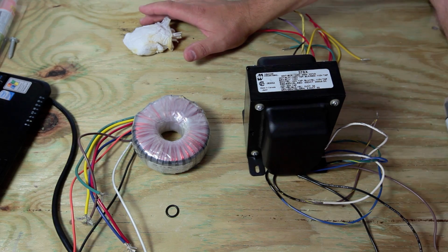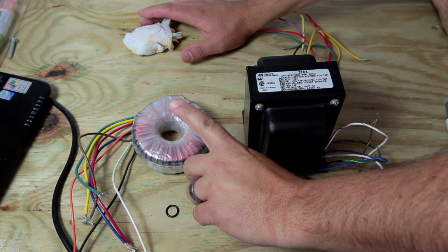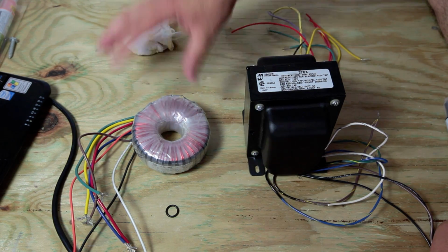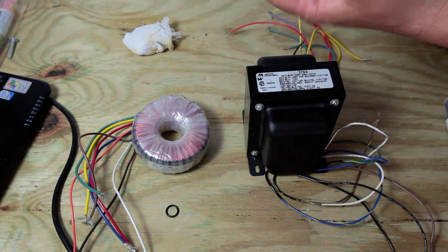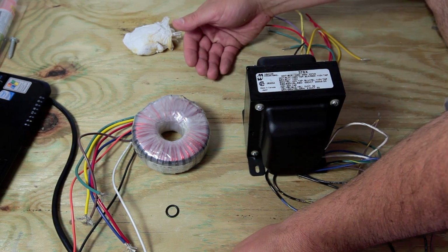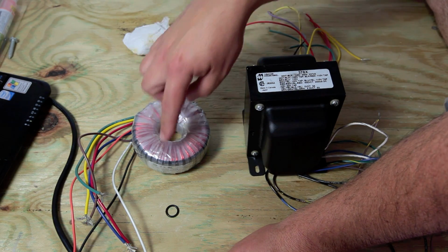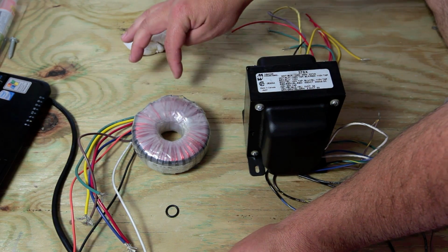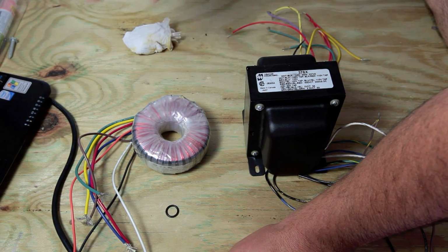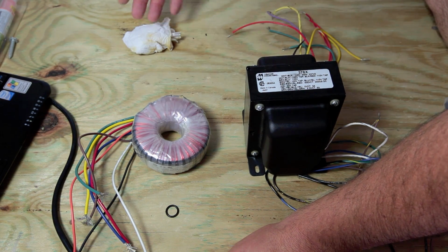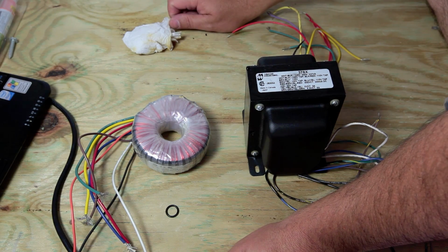They're intending to focus all of the flux within the core material. Now, how do they deal with eddy currents for this? Well, the material is powderized and then powder cast, and so it's actually not a solid conductor, not a solid ferrous material, so eddy currents don't really form within the core material. Yet it still maintains the ferrous property that allows it to focus flux, okay?